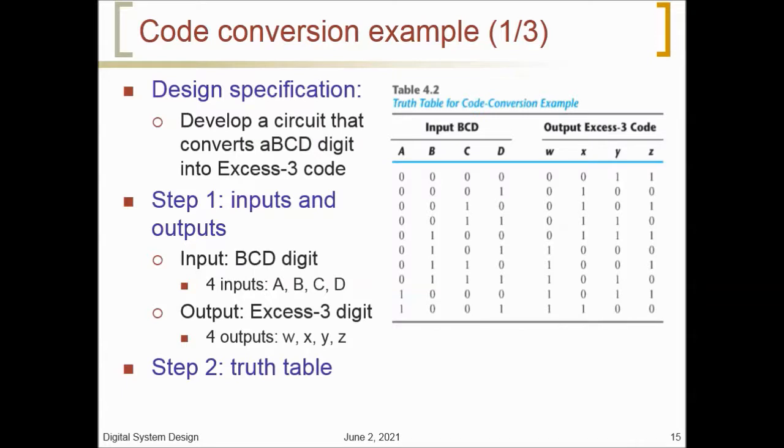To convert from binary code A to binary code B, the input lines must supply the bit combination of elements as specified by code A, and the output lines must generate the corresponding bit combination of code B. A combinational circuit performs this transformation by means of logic gates.